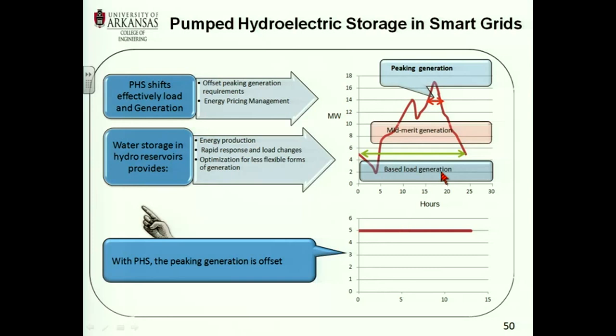this is this diagram, right? This is the load curve that you have, right? You go there, and here you have base load generation, right? That you don't want to change. Here, really, you need only this. What you do is the difference, where you use this power that the base load generation is giving to charge the reservoir.